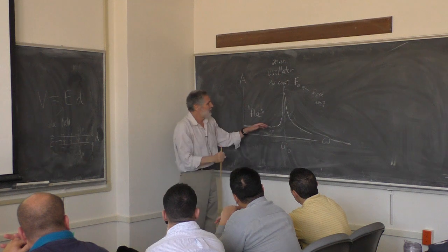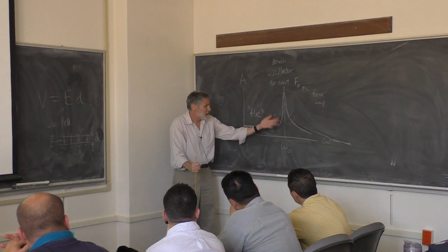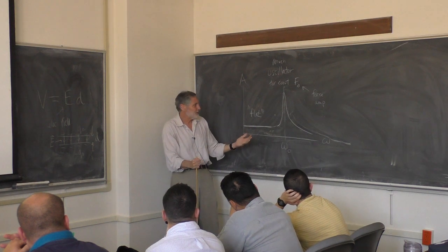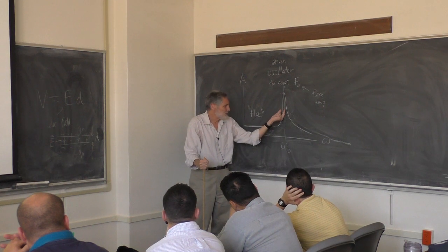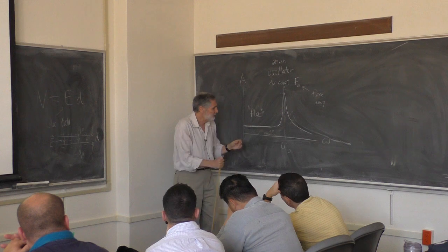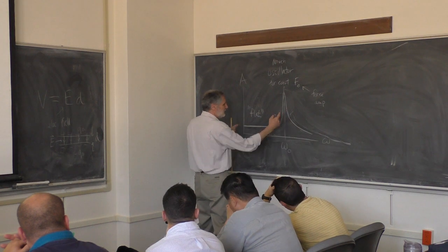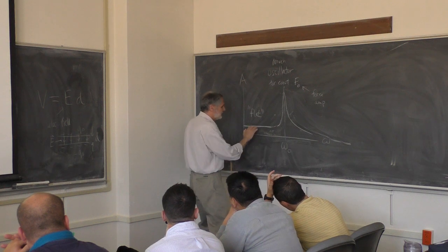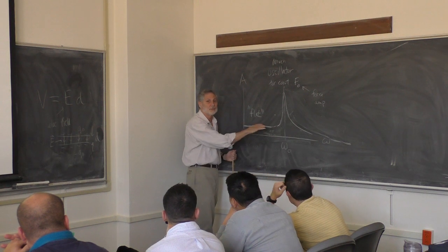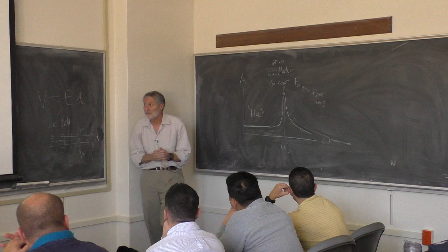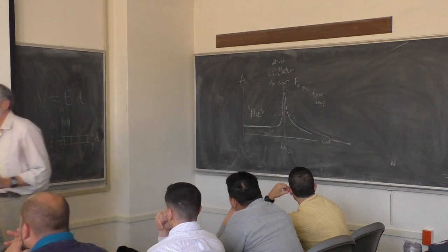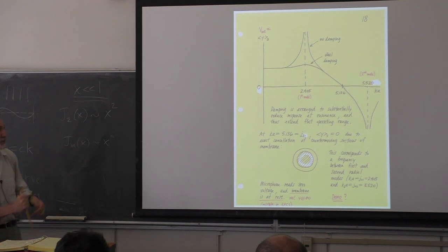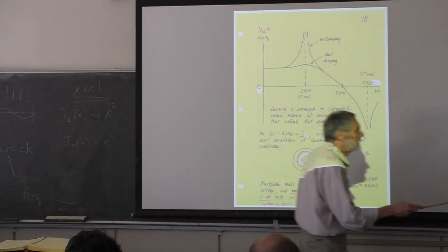All right, so this is the typical case where the quality factor is not of order unity. And you know that's going to be the bandwidth here. The quality factor is basically what the width is here compared to this. So as long as you're not in very low quality factor, there's this nice flat regime here. And this is where you want to operate the transducer. But that shouldn't stop you, especially when you're learning about transducers. You shouldn't restrict yourself to this.